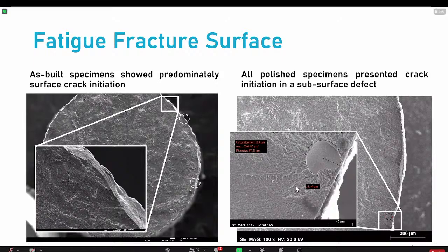It seems to start very much on the surface, as we have seen from other talks also. Well, that will depend on the material, of course, and also, in relation to this study, on the surface preparation. Since in very high cycle fatigue, you are very dependent on small stress concentration points, sometimes present in defects or on the surface.